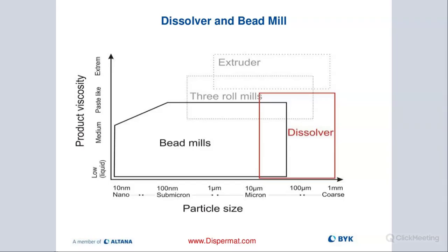So here is a visual, a table or graph that shows us the sweet spot, and at what point the dissolver with the blade is most effective, in what range, and then what range we would need to start the milling cycle. Depending on the material and the formulation, we have a sweet spot from about 10 to 30 microns of particle size. That is the optimum range to work down with the dissolver. Anything smaller is when we actually would need to start the milling process.